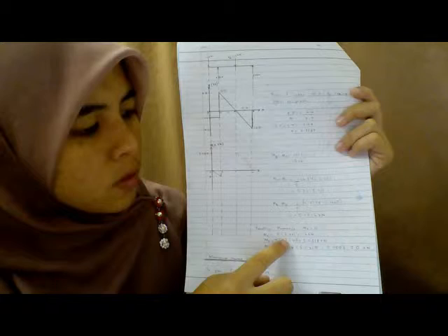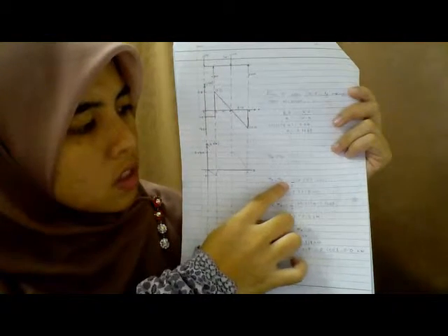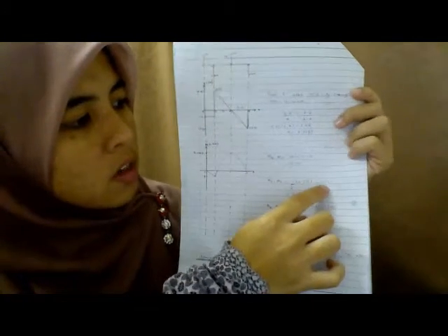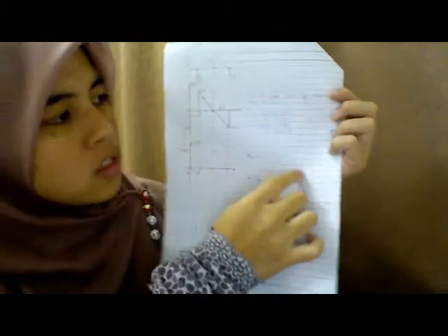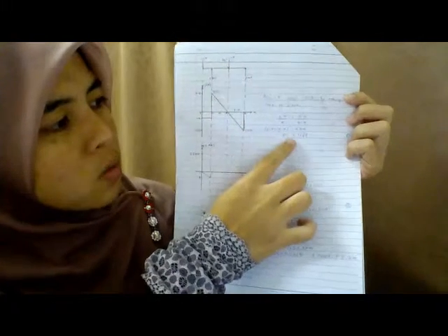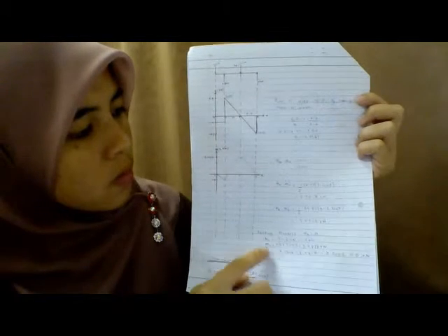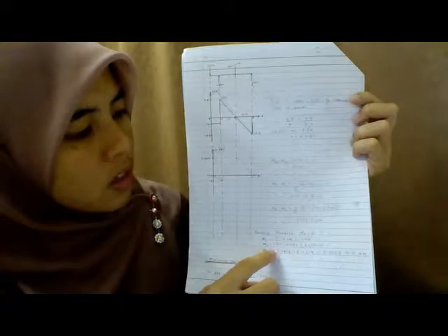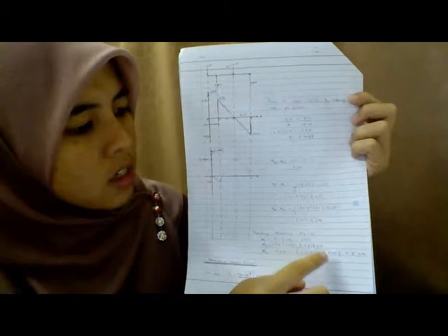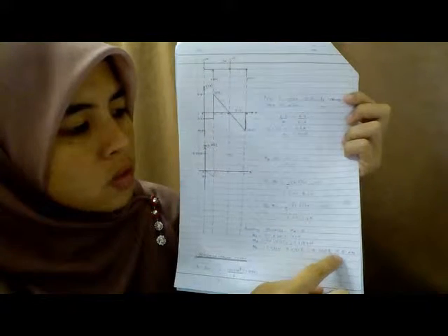The value of 7.04183, we can get it when MD minus MC is half times 6.5 times 2.1667. The value of 2.1667 is the ratio between these two figures. Then we can get 2.1667. And then for the moment at B here, we can get it when negative 5.0416 plus 5.0418 is equal to 0.0002, which is equivalent to 0 kilonewton.